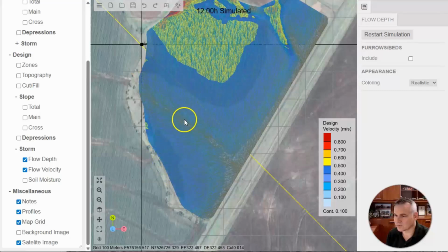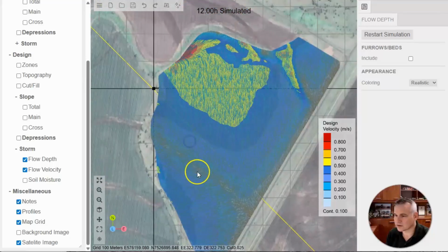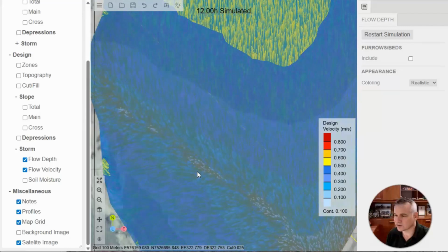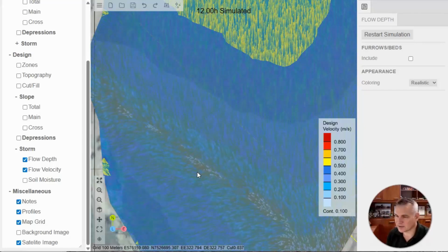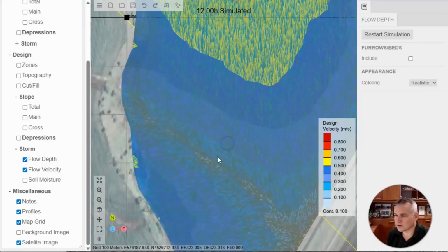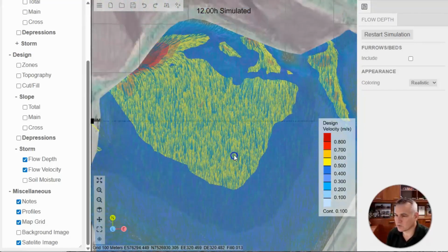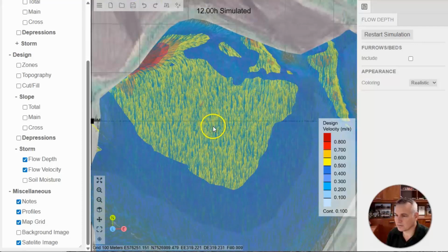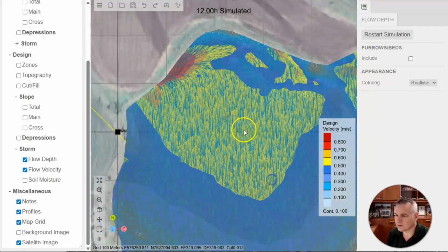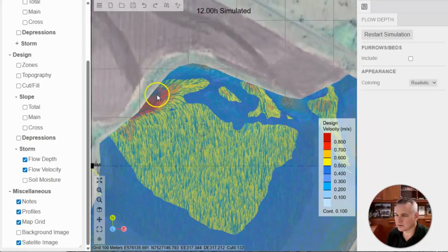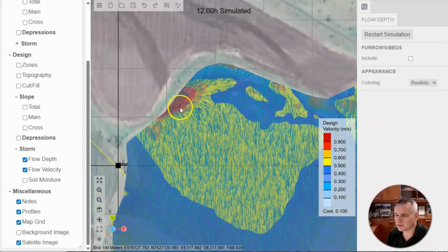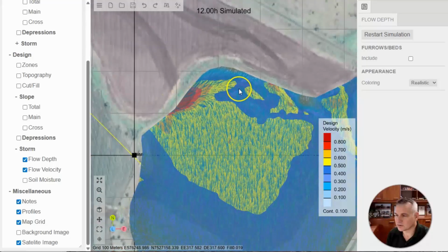The water's dispersing to the side, and it's not concentrating. Even 50 millimeters deep in the wheel tracks is enough to concentrate it. It's spreading out more. Here we do have a bit of risk, but there's only a speck of orange there, and here is where it gets steep too.